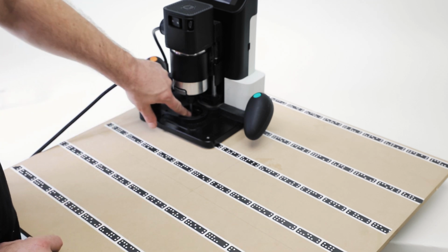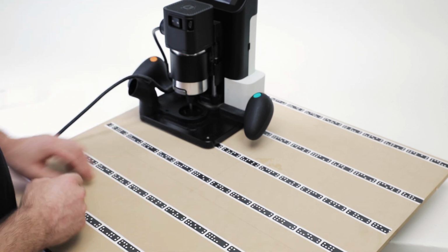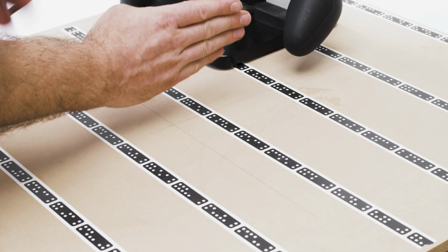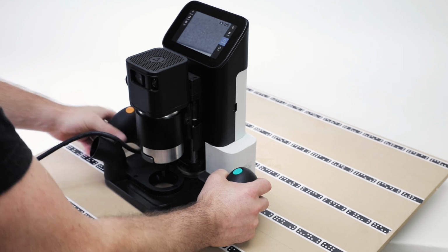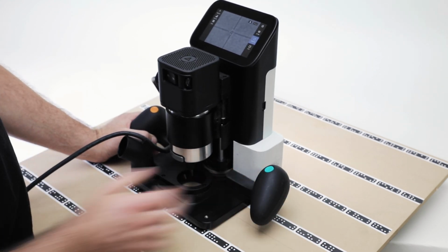So we're going to be looking at a cutter, an engraving cutter inserted normal way up. So the point is facing down, and we're going to use that point to align to pencil marks on a panel. So this doesn't make a lot of sense here, but if you're in the middle of a large floor and you've got a pencil mark that you want to align to, this gets us a really high level of accuracy. So I've scanned this in.